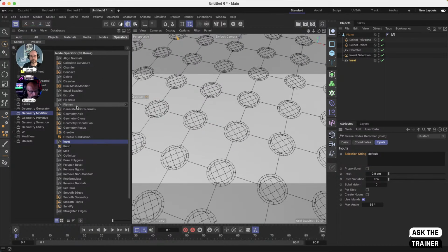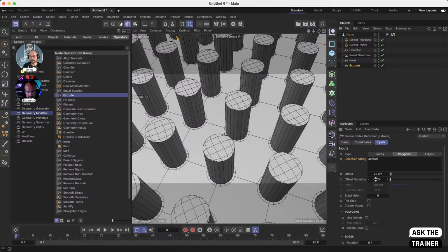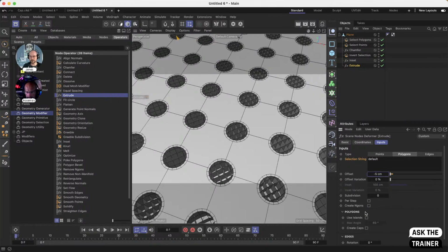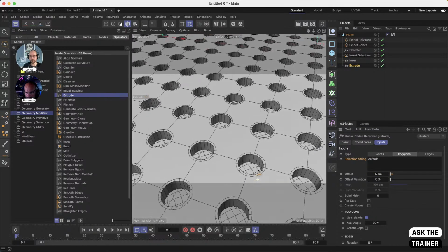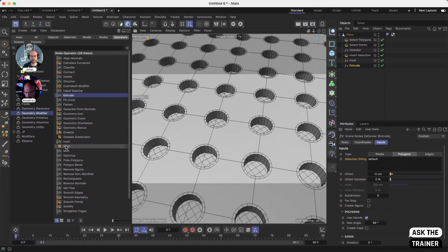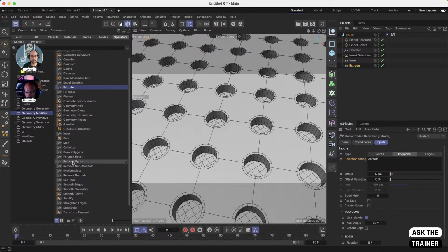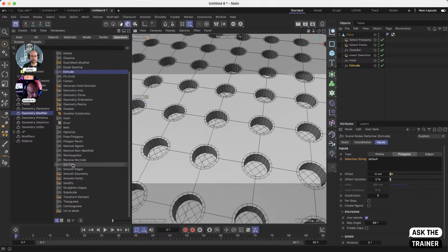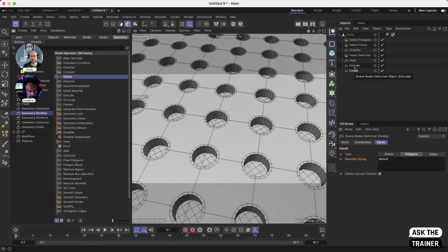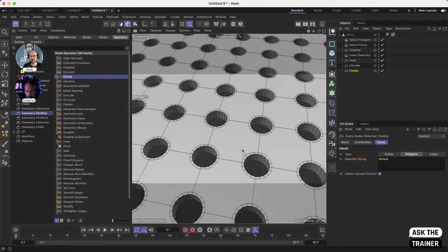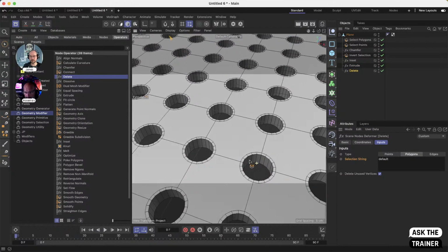The next thing is we can extrude this, like so. We just set this one to -5, for example, and also use the islands. Here we go. You can see where this is going. One thing that we can do here is delete polygons. When we add a delete, you can see that these polygons are gone and it's still all procedural.